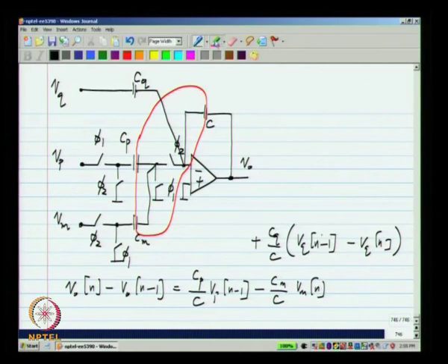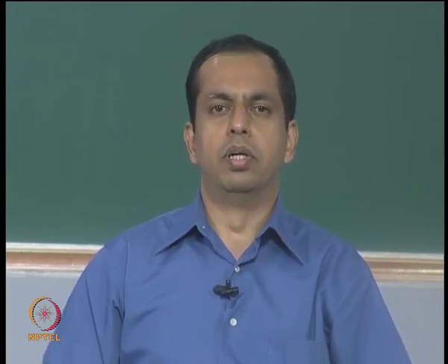So, you can implement more signal processing functions by making Vp, Vm and Vq of appropriate values and choosing the 3 capacitors Cp, Cm and Cq. So, everything that we implemented with continuous time integrators, each integrator can be substituted by this bilinear transformed integrator. So, that is one way to do it.